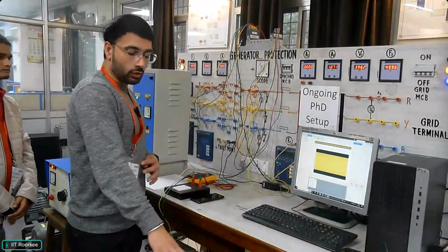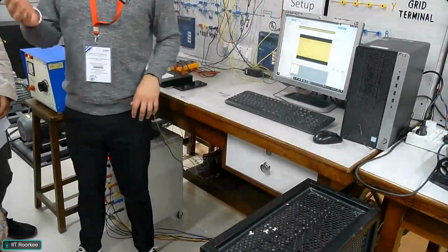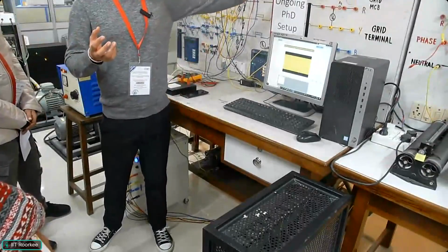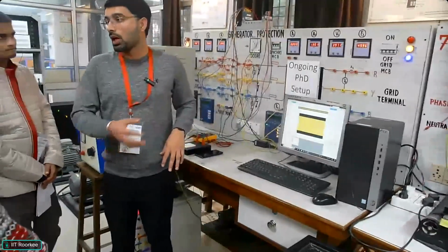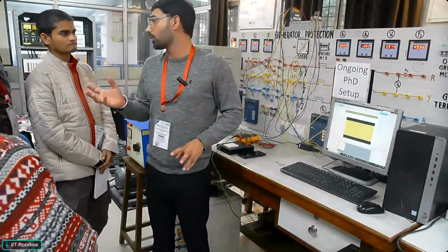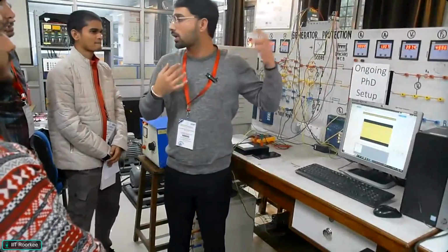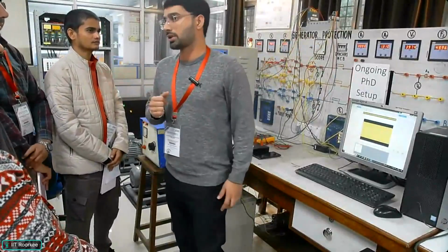All those processes I can do with the switch on load also, 1 ampere, 2 ampere, but I have to maintain that limit also for my generator, which is 4.2, and for rotor side DC shunt motor also it's like 2.4 ampere something. So I have to take care of that current also, so that stator winding or rotor windings didn't get damaged.